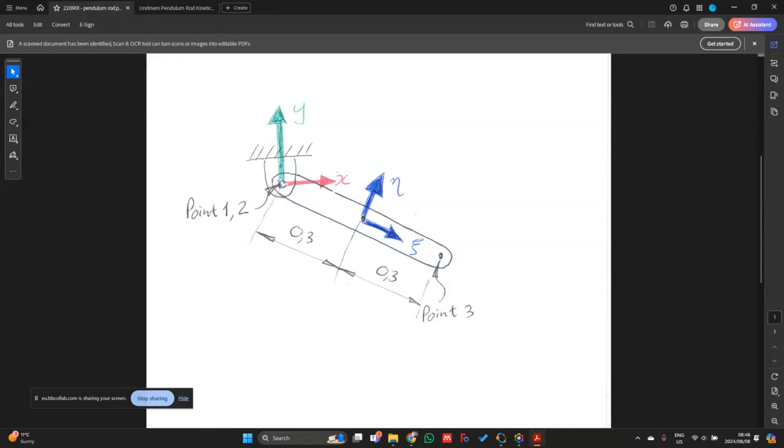the reason why we chose that is if we look at this revolute joint, which is located at the global coordinate system or the global coordinate axis, then if I have it horizontally, the maximum reach of this pendulum rod is 0.6 meters. So if I decide to instead make that limit, let's say 1 meter, I should have a large enough window to actually simulate and animate what's going to happen with this pendulum rod. So that's why I use -1 and 1.